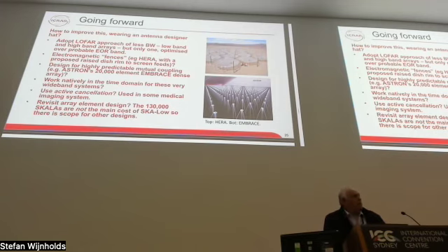Something else you could maybe do is design for highly predictable mutual coupling. Ron showed an example this morning again of the checkerboard array, which is used in ASKAP. That's an excellent example, along with Embrace's 20,000 element array, so ASTRON's 20,000 element Embrace array. These both exploit highly predictable mutual coupling, and they can do it because it's on a regular grid.